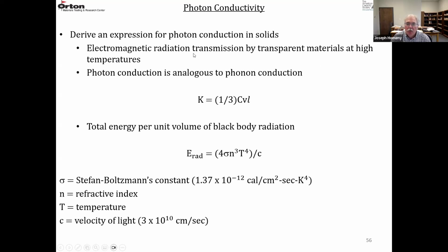And then what's important in refractory materials is pores, because you can have thermal radiation across pores. So we'll alter that equation to account for porosity and develop another equation for radiation in refractory materials when there's porosity present. And just about every refractory material, unless it's fused cast, has 10 to 20% porosity.